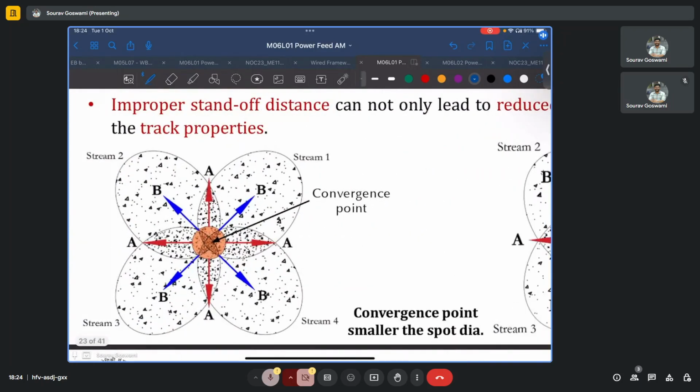So in this first case here, we have these powder streams. The ellipses are the powder streams. They're elliptical because while the powder stream may be circular, the channel has a circular cross section. Because of the inclination of the channel with the flat substrate or build plate, the projection that we get on the substrate is elliptical.